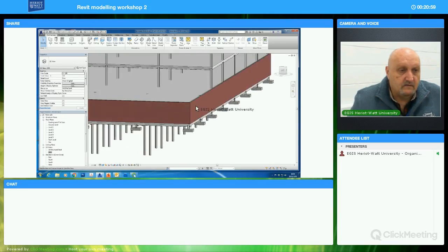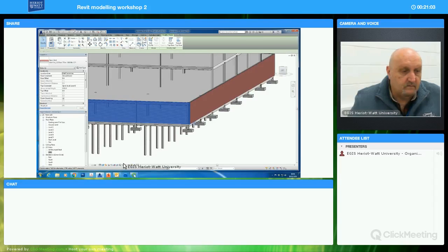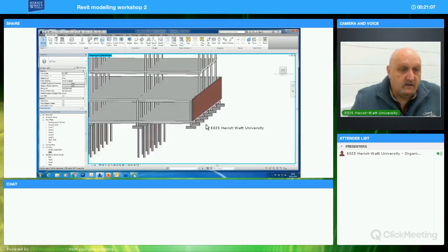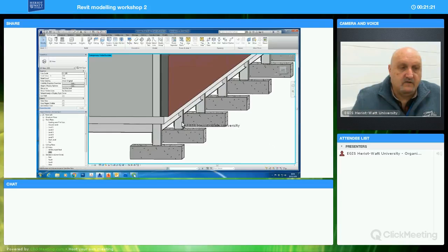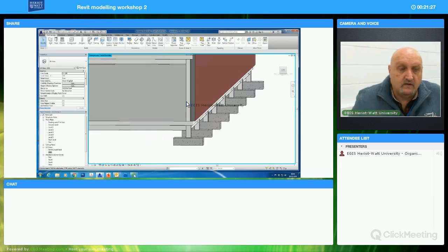because the ground floor is going to be different. If I hide off one of these, that'll maybe help. Hide off that wall for a minute. If you have a wee look in here, you'll see that this floor here eats into this wall, kind of takes out the geometry of half of the wall, the inner skin of the wall. It maintains the cavity, but here it looks as if this wall isn't fully supported by the ground floor, and that's because it isn't fully supported by the ground floor.